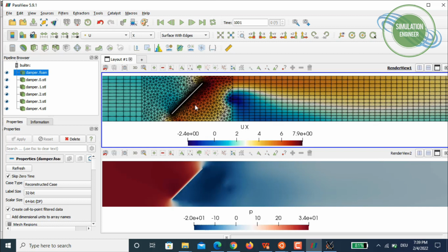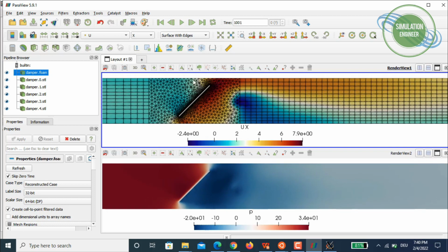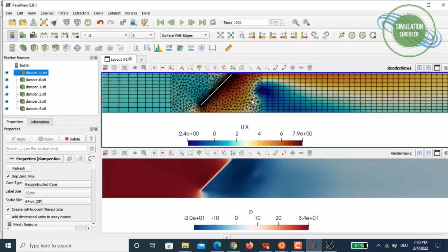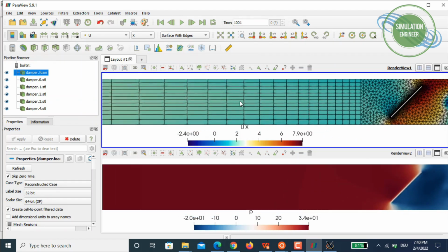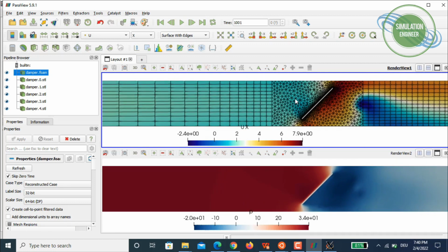It's in between coarse and medium, you could say, but there is still a tendency to go for further mesh improvements, especially just behind the damper, the downstream part of the damper, because we have a very large domain. On the other hand, extending this domain in the upstream direction and also downstream helps not only the convergence but also to get a really developed flow.